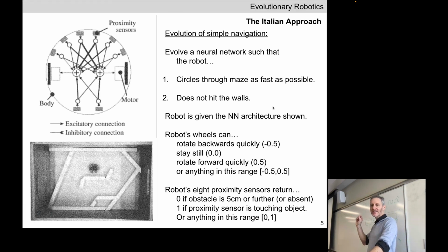These proximity sensors emit an ultrasonic pulse, and then they measure the amount of time until they hear that pulse. So this is kind of like bats and echolocation. You're going to send out a signal and see the amount of time that elapses from sending out an ultrasonic pulse and hearing its return. And then based on that time, they can infer how much unobstructed space there is between the sensor and something else.